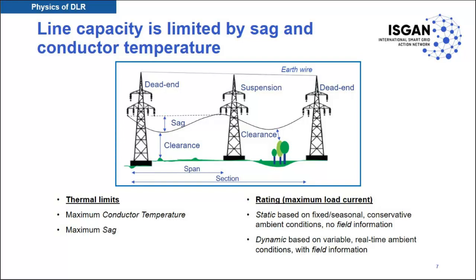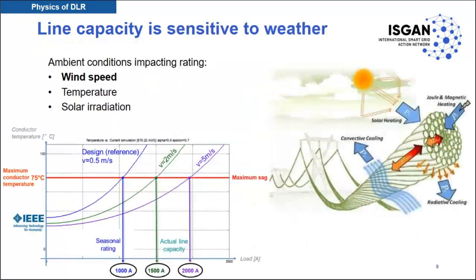I'd like to say that it's very simple, and it's quite nice, and thank you for listening, but it's not so simple. In fact, if you see here on the right on this drawing, it's a CIGRE drawing, and you see that the conductor is in a thermal equilibrium affected by solar radiation, obviously, ambient temperature, the line's load, the current going through the conductor, and cooling by wind.